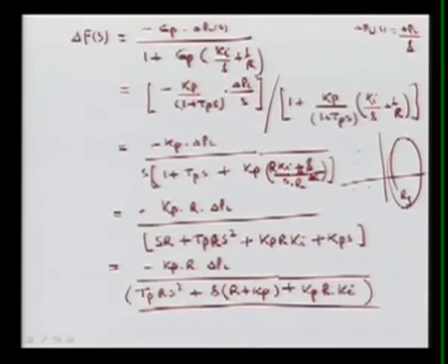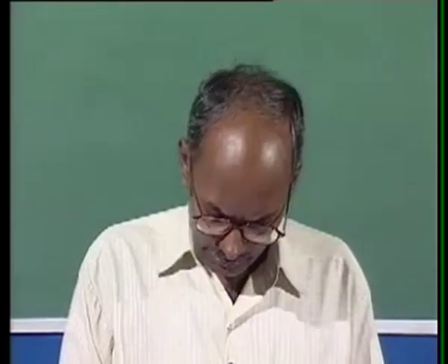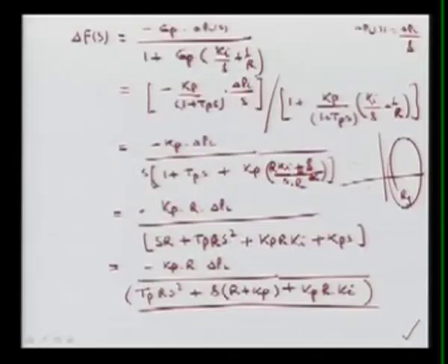We don't want the unstable side; here is the stable side. To see the performance, we can draw the characteristic equation and then decide what the gain should be, because this critical Ki is very important, which decides the criticality, the overshoot and the underdamped performance of the system. The denominator is also known as the characteristic equation. This gives information on whether your system is stable or not. Let us see what we get in the characteristic equation.